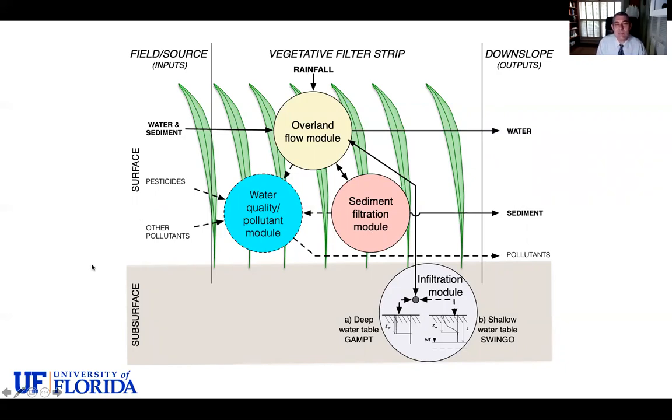So all these things from the source area are input into the model. The model then routes the water through the overland flow component, which ultimately responds to a hyetograph, essentially a dynamic rainfall pattern during the event, the short run event. The interaction between the rainfall and the infiltration determines how much water keeps moving on the surface in every node of the finite element mesh.